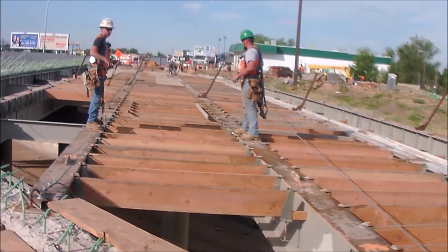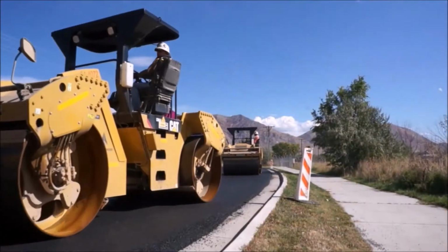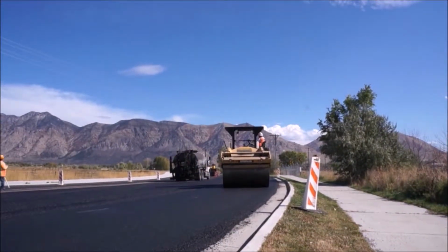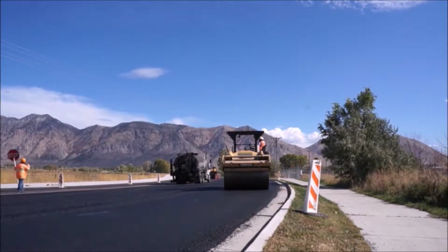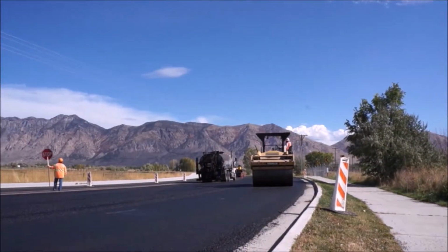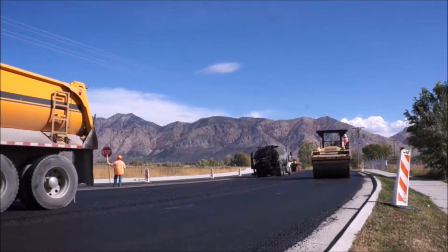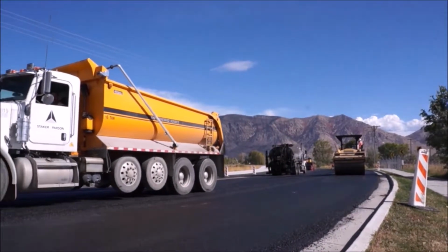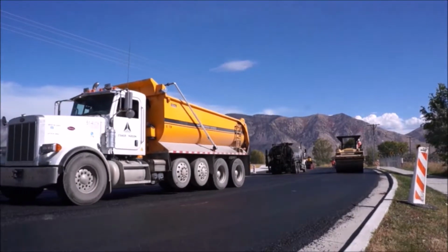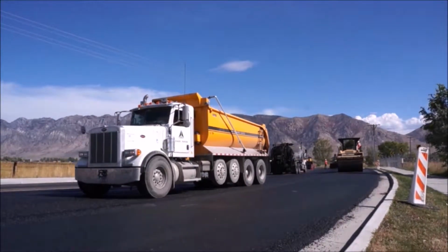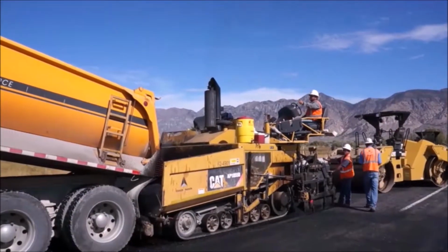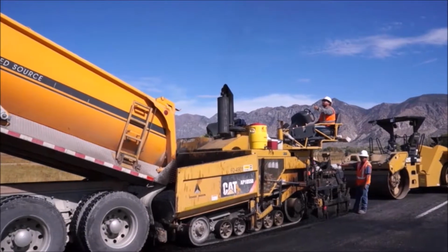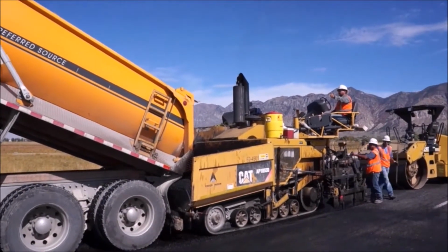We begin our site-specific hazards with internal traffic. Phasing impacts the size and shape of our work area. Internal traffic pattern must be accounted for prior to starting work daily. We will use some sort of separation between workers and internal traffic when a significant hazard exists. We will use cones for paving, glow sticks for night paving, and other signage or physical barriers as appropriate.